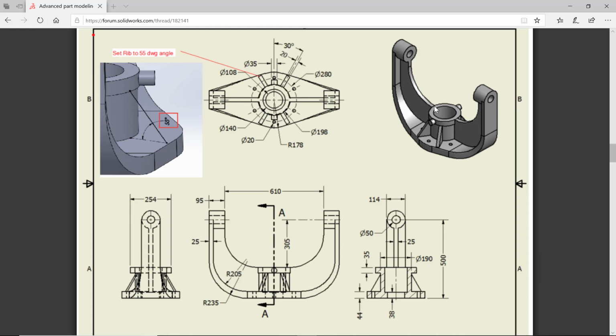And then if we had an imaginary line across here, a line that was tangent to it, we wouldn't need a radius dimension on the arc. It would all fall into place. I have to decide whether to start from the top view or the front view, and either way, I guess, would work.